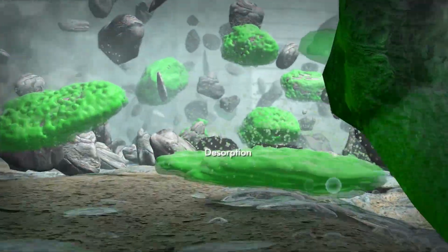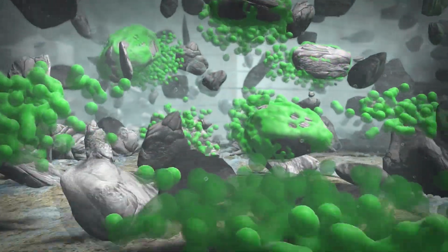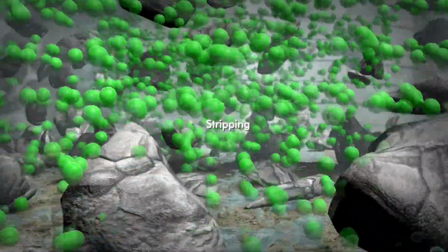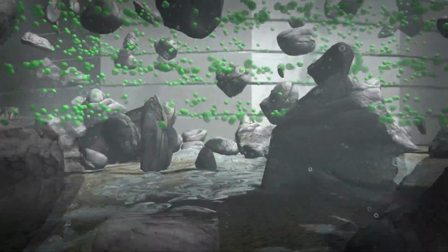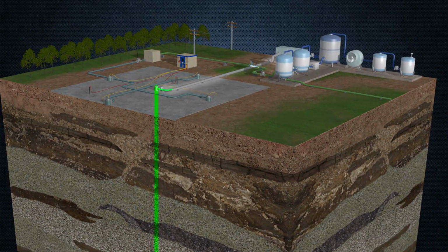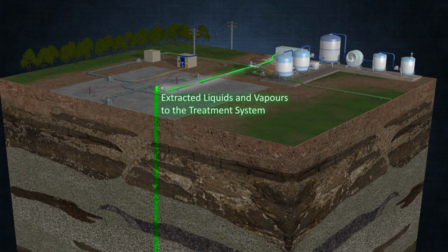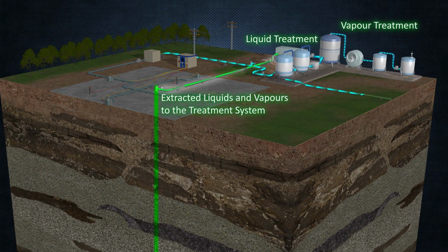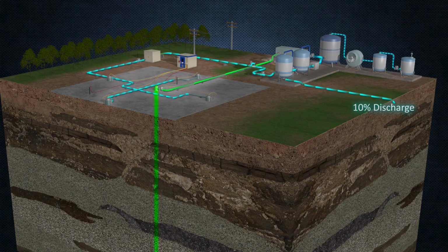Extraction wells with properly designed well screens operating under vacuum pull the vapors and liquids rapidly from the soil, leaving the silts and sand material behind. The ET DSP system, operating with a conventional multi-phase extraction system, in effect compresses the operating time to reach desired remediation goals from decades to months.